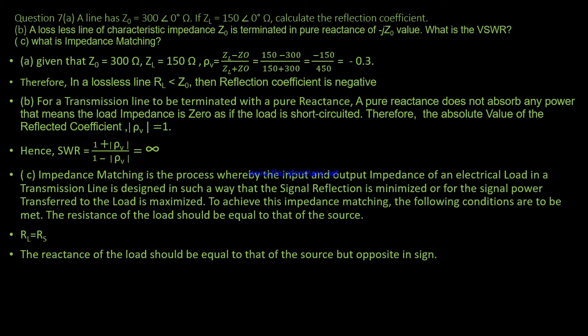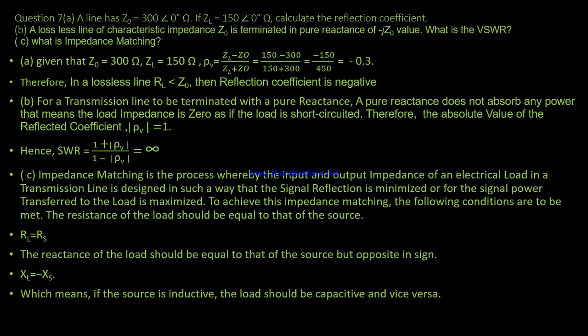Number two, the reactance of the load should be equal to that of the source, but opposite in sign. So the inductive reactance must be equal to the capacitive reactance in an opposite sign, which means if the source is inductive, the load should be capacitive and vice versa.